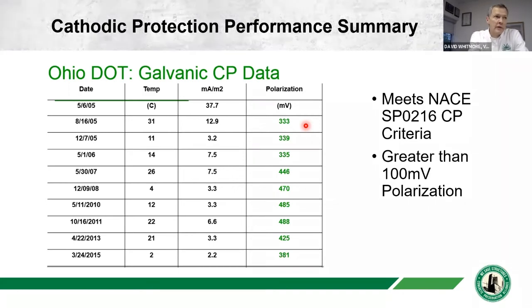I mean, we do impressed current cathodic protection. Obviously we do galvanic, which we've been talking about here today. I have seen situations with impressed current, particularly with discrete anodes or with ribbon type anodes, where because of gas generation at the anode, we've had some bubbling on coatings. But that's because you're generating gas either at the anode or at the steel.